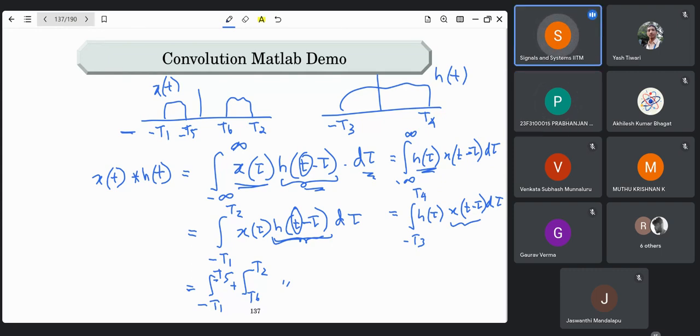For example, if you are a telecommunication engineer, then this notion really helps to understand what happens to signals that you transmit when you represent baseband signals. Then what is the signal to noise ratio when you define them? In those scenarios, these definitions of energy will come into play. So think of this as just defining the length of a vector. The energy of a signal is equivalent to the length of a vector, where the vector is the signal itself.